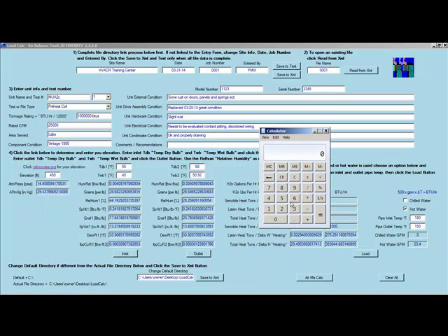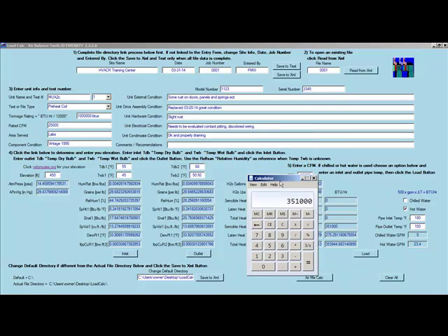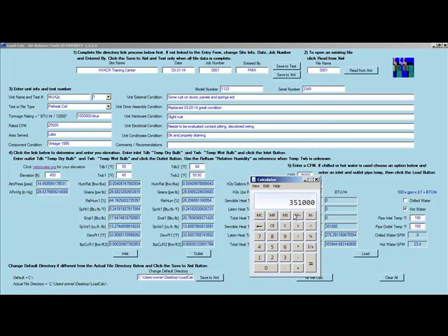So if we said 500 times 23.4 and delta T of 30, times 30, and because we're doing sensible heat, we're not adding any moisture, this is the number we're using, the 35.1.